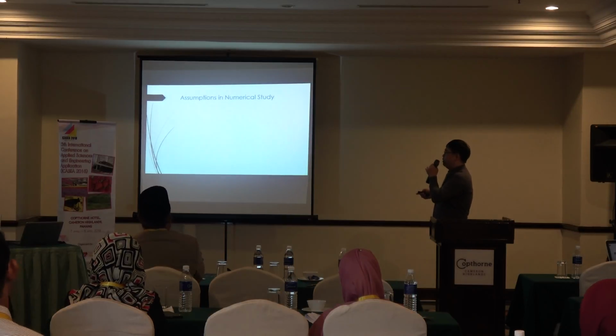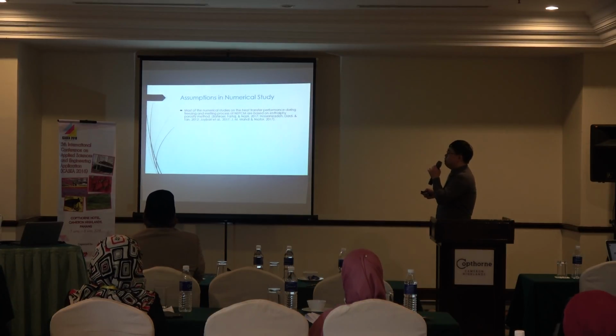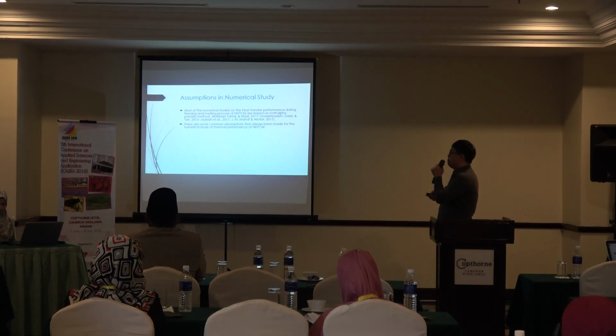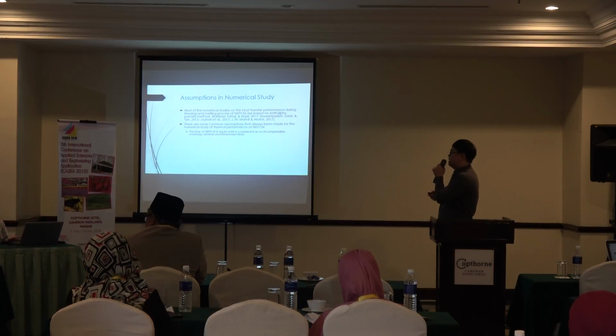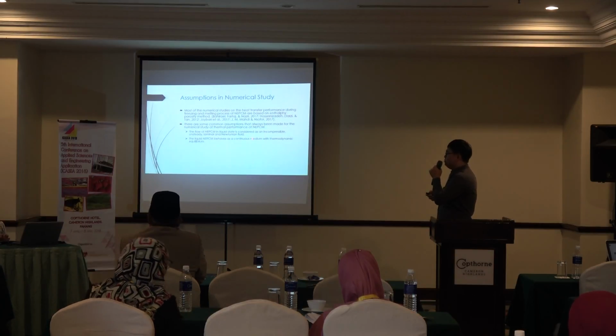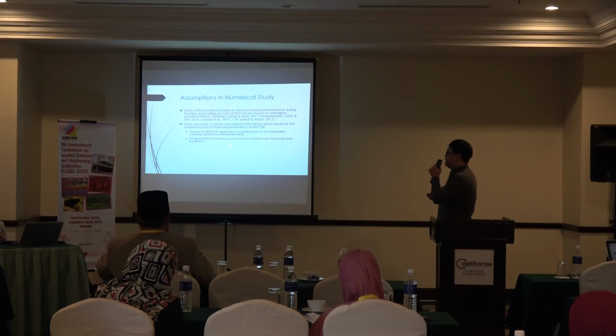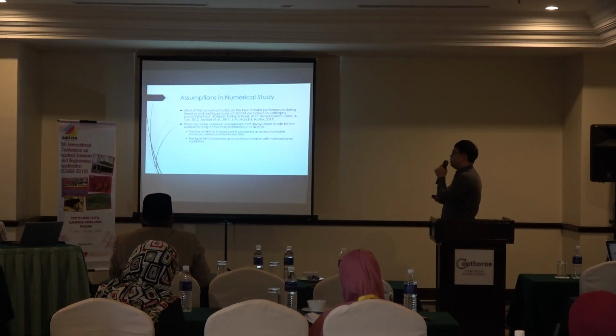From the review, I also found that most of the numerical studies on the heat transfer performance during the freezing and melting process are based on the enthalpy-porosity method. There are some assumptions that we make for the study: the flow of the liquid PCM is considered as incompressible, unsteady, and laminar, while the liquid PCM behaves like a continuous medium with thermodynamic equilibrium.